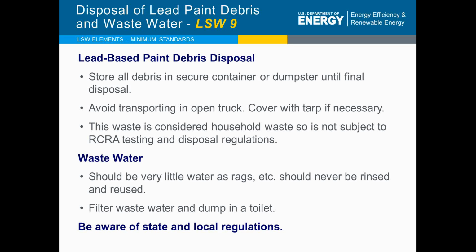For cleanup, any wastewater that's generated must be filtered. We use paint filters for that. The paint filter and the debris go into our debris bag, and the filtered water is then poured down the toilet. So you have your solid waste and your water waste, and those are the correct ways of dealing with it. Just as a point of reference, if you were doing, not LSW work, but RRP work for non-residential, you cannot store any more than 220 pounds of that waste before it's classified as hazardous waste.